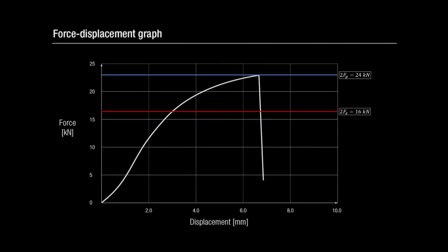This is the force displacement graph. It shows an initial linear elastic response. In a clear wood beam with no defects, the tensile strength is much higher than the compressive strength. So, as the wood in the compressive zone begins to crush, the bending behavior becomes nonlinear. Therefore, some redistribution of stresses takes place until the ultimate tensile strength is reached at around 24 kN, which is the same as our estimation of the collapse load based on the pure plasticity theory.